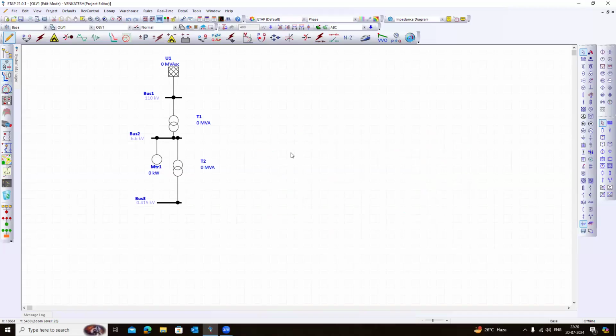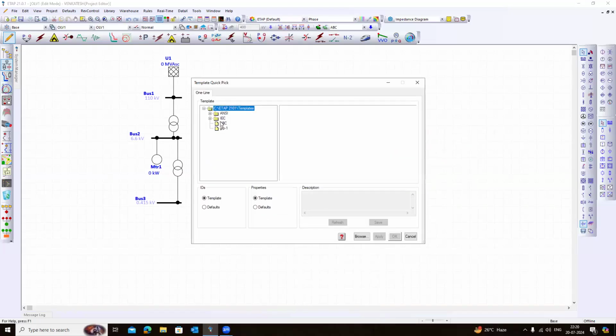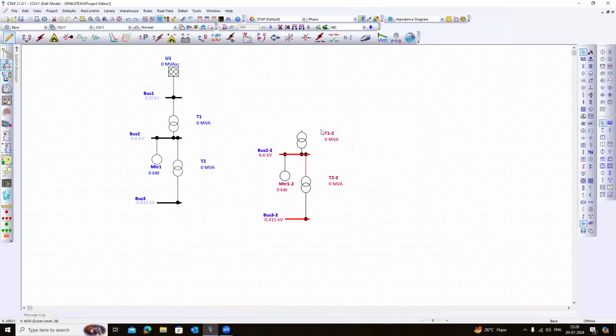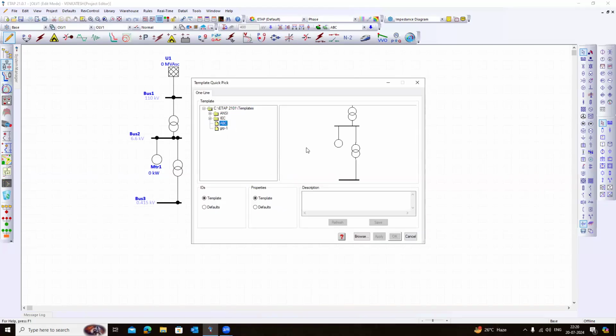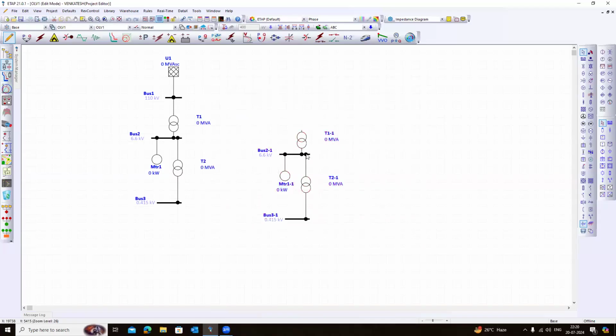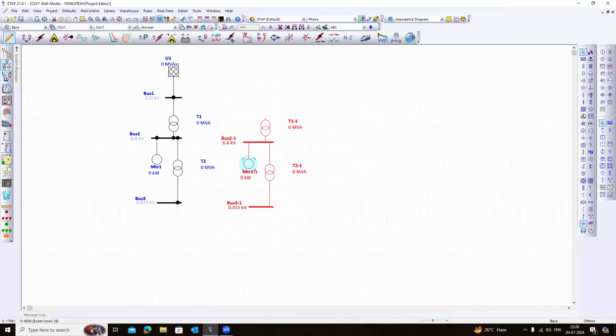Let's do it, shift delete, template get from ABC, click apply. Or then don't do this apply option. I think when you are clicking that apply, it is getting this one. Select this, click on OK. Okay, like this. So now you can connect it to the grid or wherever you want, you can connect this. So this is another way of creating or replicating a set of branches as per your requirement.